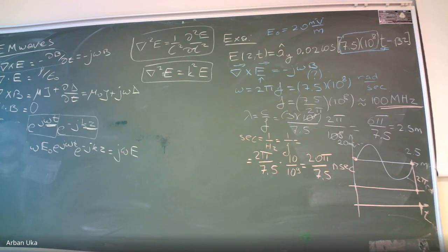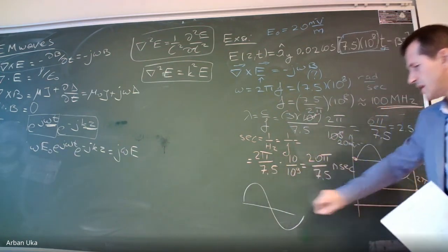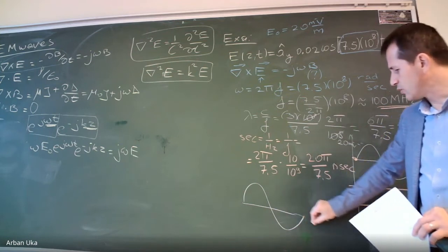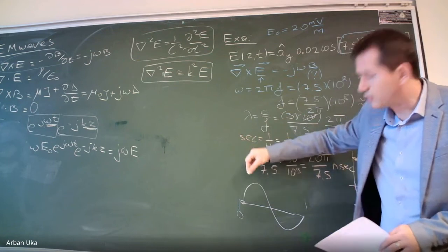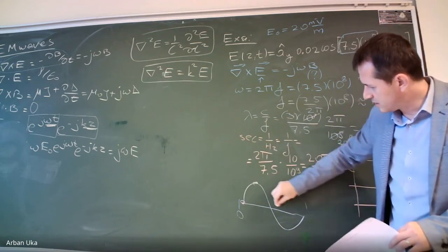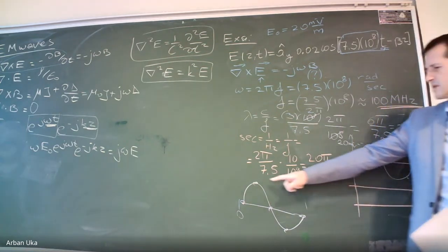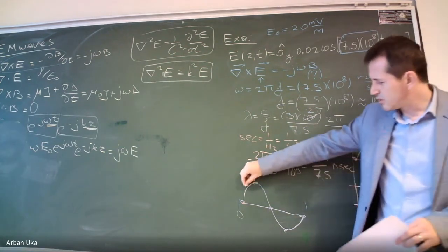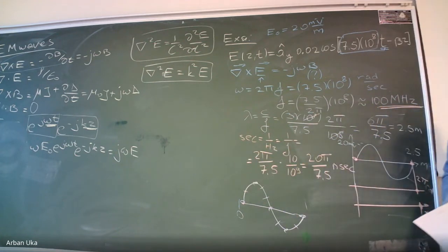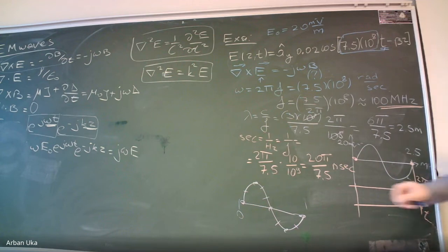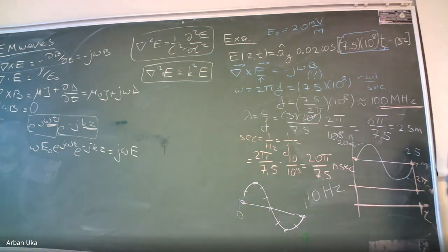Okay. Now, let's say that this is our wave that we want to measure. It takes 1 second from time 0 to 1 second. And then you need 1 data point here to read out the 0, 1 here, the second, the third, the fourth, and the fifth. Okay, so we need these because if you miss this it might not be good. Then you start to read again 5, 6, 7, 8, 9. You pick another data point here, 10. That's good. So that means that to pick up a signal at 1 hertz, you need to read at 10 hertz, the sampling rate. How often you're going to measure.